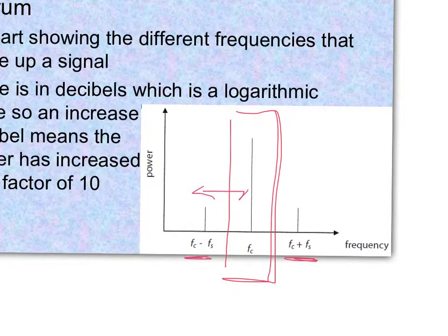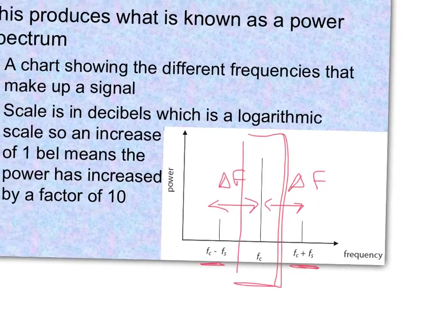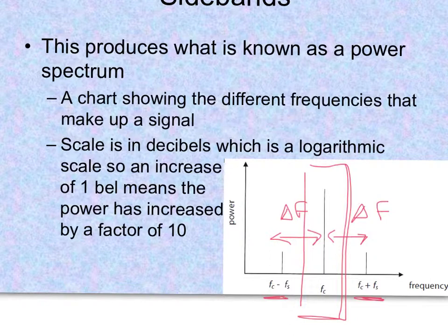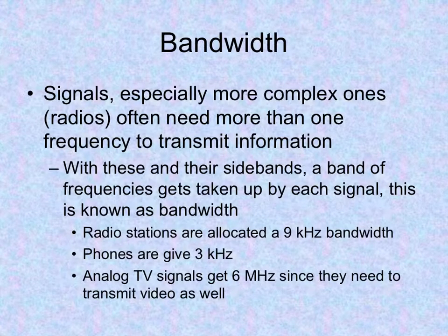And this area right here and this area right here, that change in frequency or that difference in frequency on either side is the same. And as you look at this power spectrum, one thing to keep in mind when we're talking about these, we're using what are called decibels. Okay, same thing we talked about with sound. And decibels are a logarithmic scale. And so what that means is that when you increase the power by 1 bel, you're actually increasing it by a factor of 10. Okay.